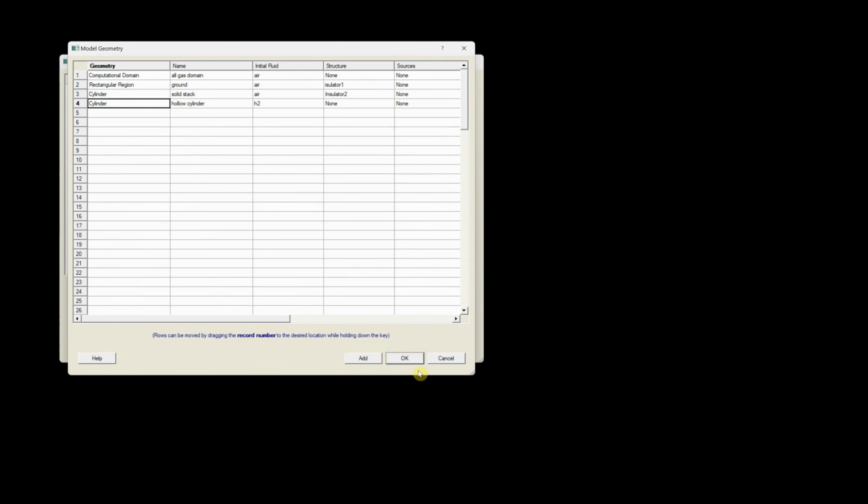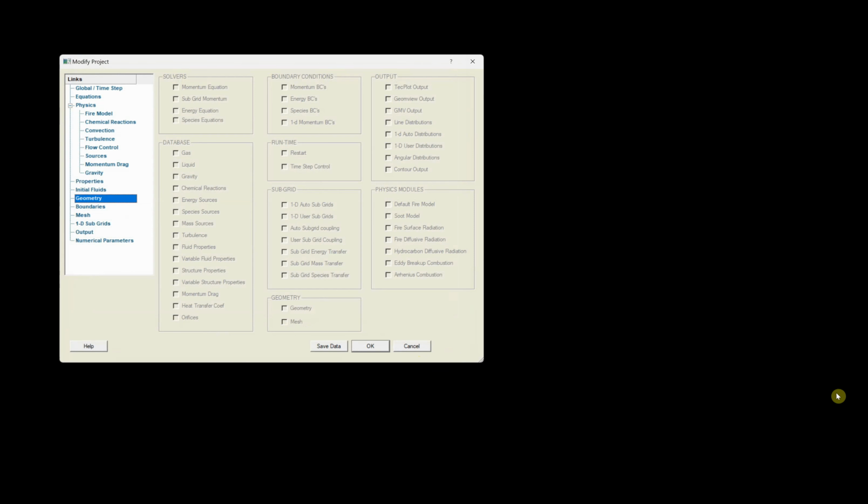And it goes from the very bottom of the domain, because we want to cut the hole through the ground as well, up to the top, 15. And it's going to be hydrogen gas, so we don't have to fill it. And that radius is the inner diameter of that stack in the experimental paper, or 0.22 meters in radius. Okay, that about does it for the geometry.